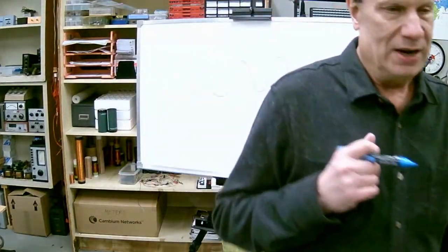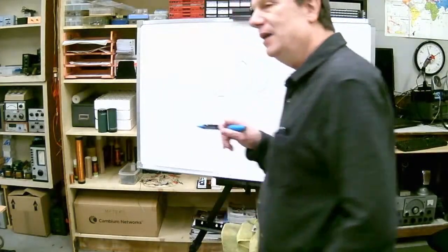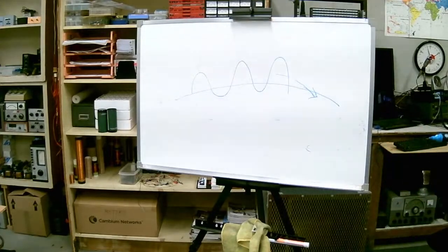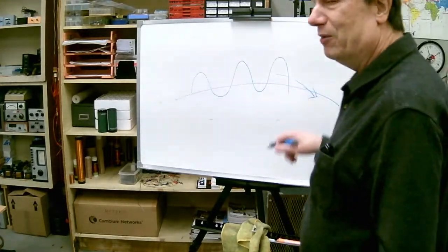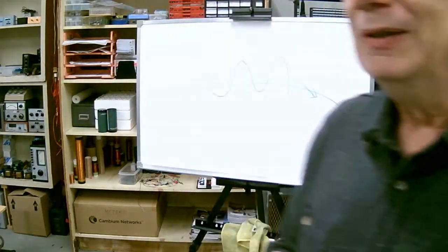Vertically polarized antennas, vertically polarized waves, are the only ones that will travel in contact with the conductor like the Earth. If it's horizontal, it'll just short out. So you cannot get ground wave propagation with horizontal polarization. It'll short out. Interesting.